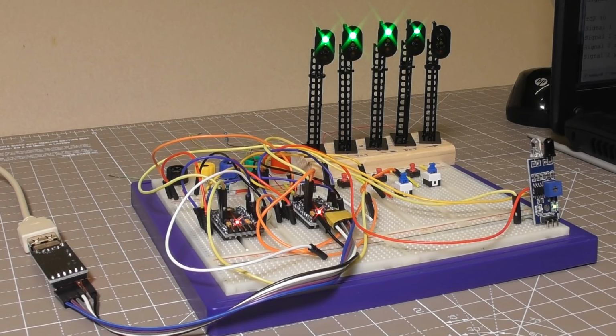Each one will have a sensor after it, just the way they do at the moment, one of these sensors. But because the train will pass over both sensors, one in the right direction and one in the wrong direction, we can use that to our advantage, and we can then force all the signals in the non-running direction at this moment to red, and then only signal the train through in the other direction with red, amber and green, if that's what we're going to do. So that's what I'm thinking about.